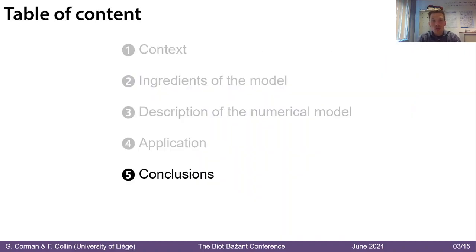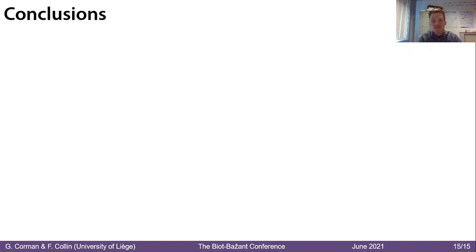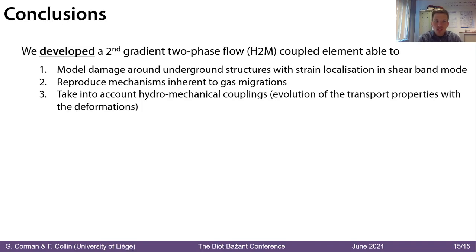This is now time for the conclusions, and we have seen that the geological disposal of radioactive waste is a seat of complex multi-physical processes that can interact with each other. Accordingly, we have developed a second gradient two-phase flow coupled element able to model the damage around the underground structures with strain localization in shear band mode, and also able to reproduce the mechanisms inherent to gas migration while taking into account all the related hydromechanical couplings.